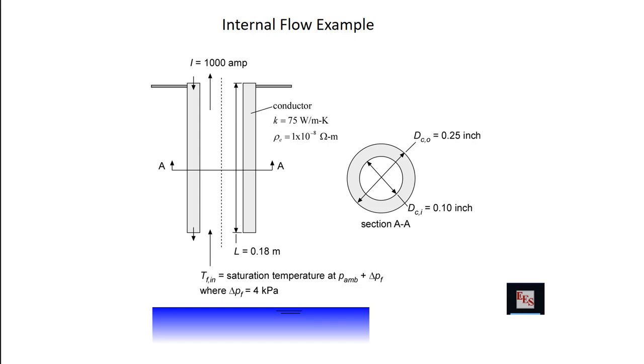flow goes through it. In your homework, and in almost every problem you'll do, you'll hook a duct up to something more like a pump, where the pump will give you a pressure rise across the duct, and that pressure rise isn't just a constant. It depends on the flow that you're drawing from the pump. And then your duct is going to give you a pressure drop that isn't constant. It depends on how much flow is going through your duct. And so you have to make those two components line up. You have to make sure that the pressure and flow you're asking your pump to give you match the pressure and flow that your duct requires. That's certainly some kind of an iteration, and that's what we'll do next.